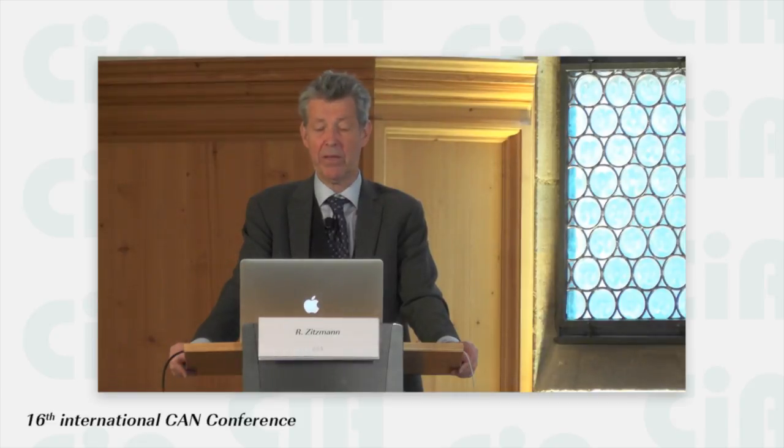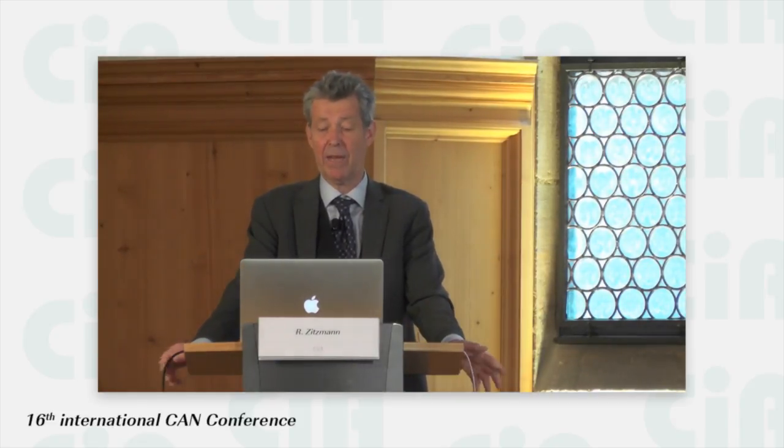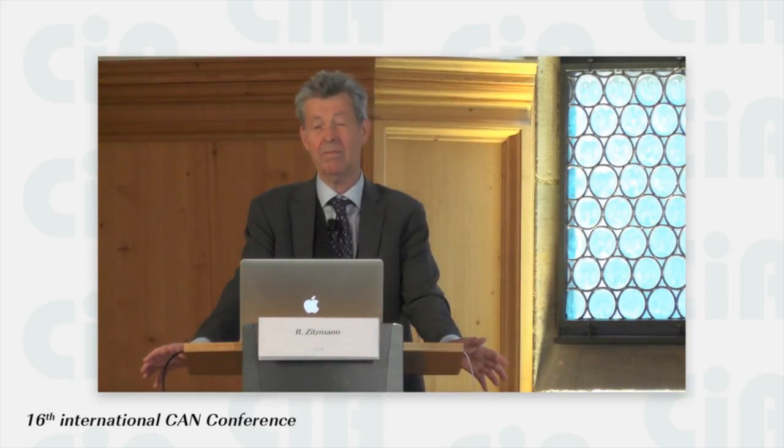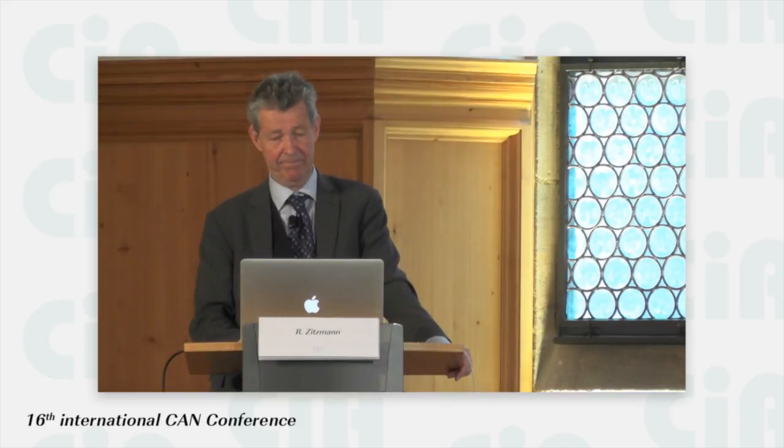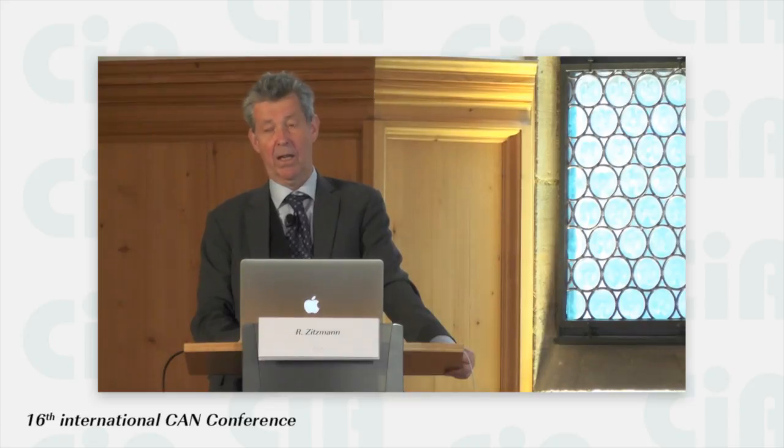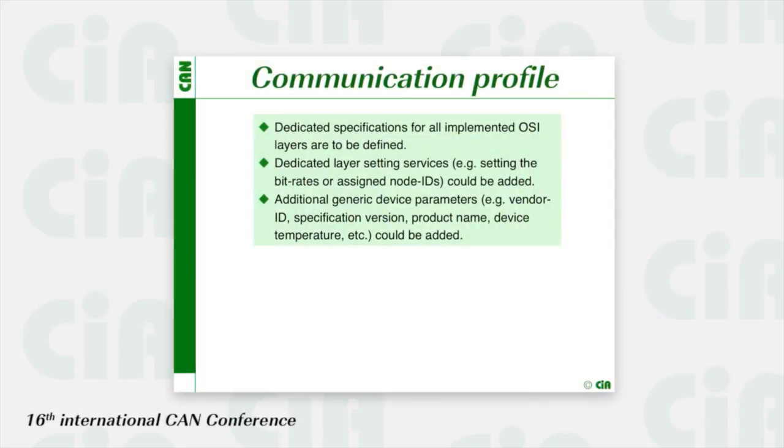The other way is what the automotive industry is doing. They invent some middleware, hiding the details of the application layer, but this increases the software overhead. You have to pay something for that. And DeviceNet has done the same for ControlNet and Ethernet with their CIP application layer. When you are mixing those things, then you have to specify in detail for each layer what you have implemented.